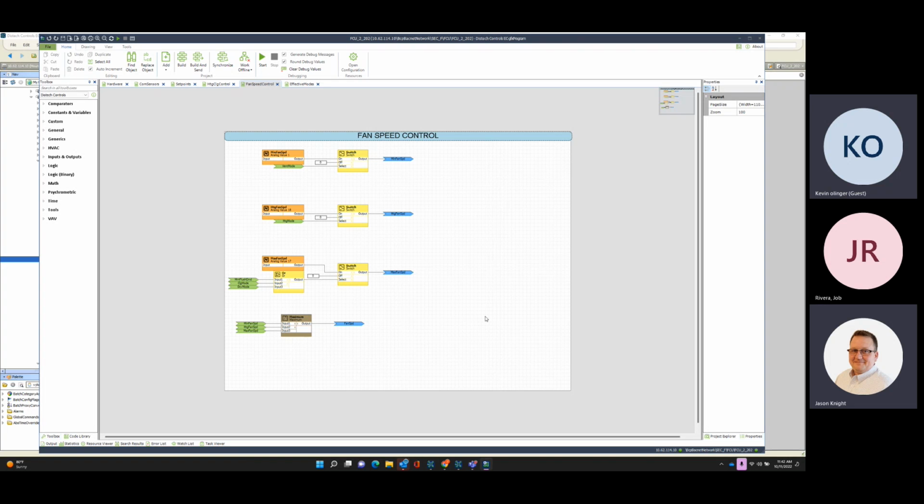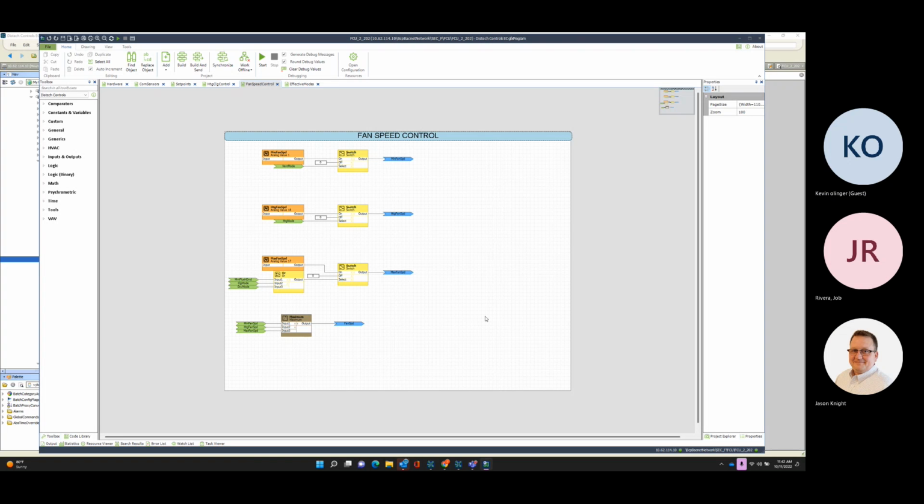Now you have some units where you have multiple motors. You have like a little mini fan wall in these fan coils. You'll have 2 supply fan motors. And they're hit and miss throughout the building. And it just depends on the size of the fan coil. There's only one current signal and there's only one status. And it's super hard to monitor. So it sounds like a little plug fan wall in a fan coil unit. So there's 2 parallel fans in a fan coil unit, right?